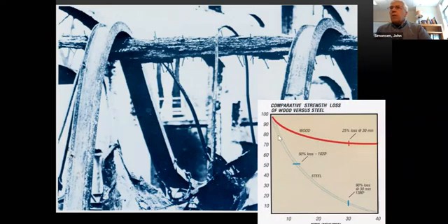So here you can see what happens to the strength loss of the steel and the strength loss of the wood. Oh, this gives you the temperatures here, right? And so you have 25% loss at 30 minutes of fire. I don't know that that's all that helpful.